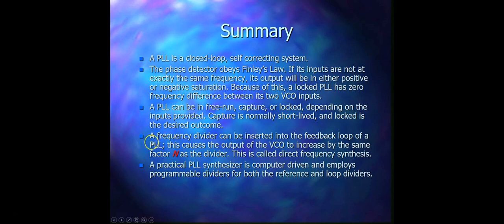The frequency divider can be inserted into the feedback loop of a PLL, and this causes the output of the VCO to increase by the same factor n as the divider, and this is called direct frequency synthesis. And lastly, it says a practical PLL synthesizer is computer driven and employs programmable dividers for both the reference and loop dividers. So this is the end of the lecture.